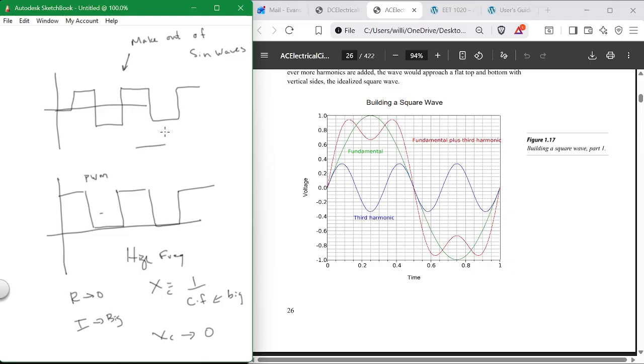If you do it like this, it's on 3/4 of the time. This would be 3/4 on and 1/4 off. This would be half on and half off. This would run at half speed, this would run at 3/4 speed, and this would run at quarter speed. Okay? Those are PWM signals. But what other signal runs on a PWM?